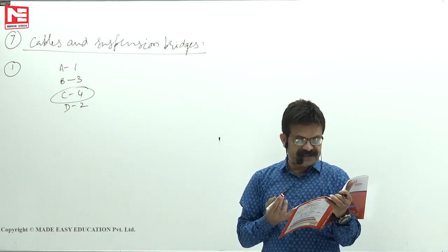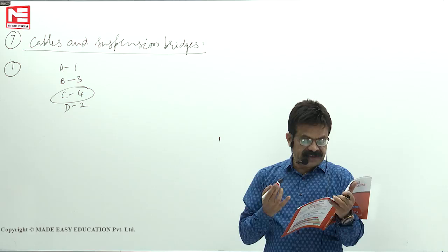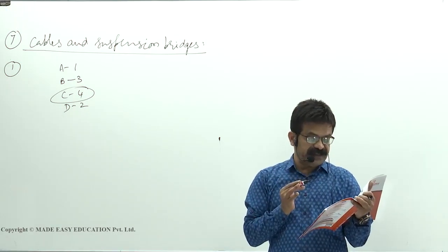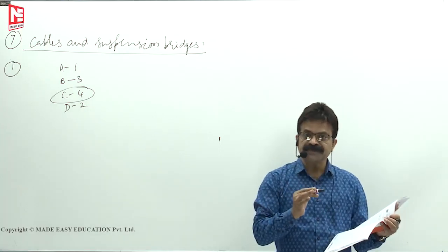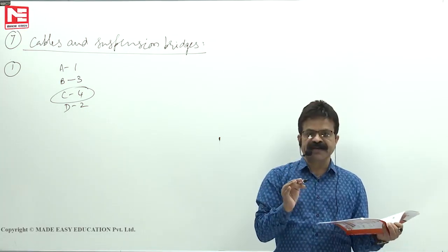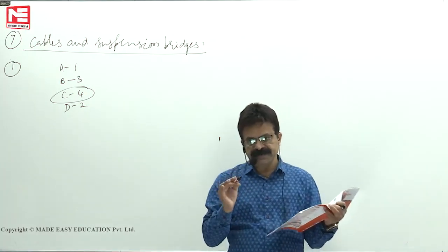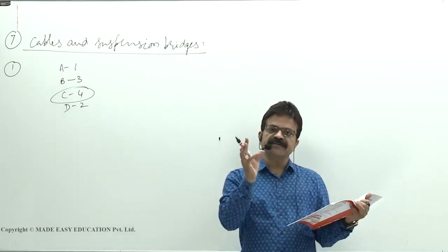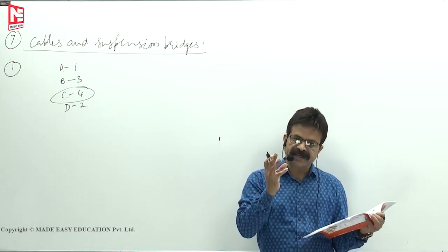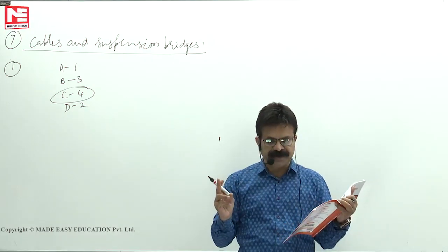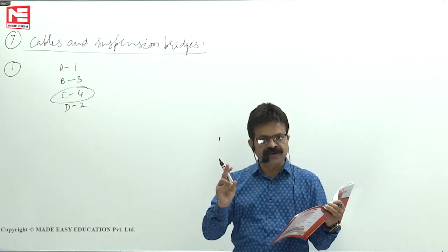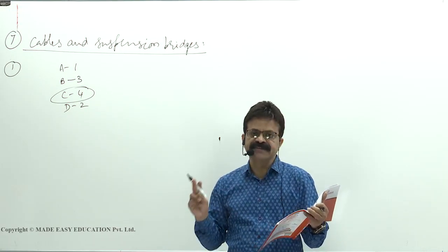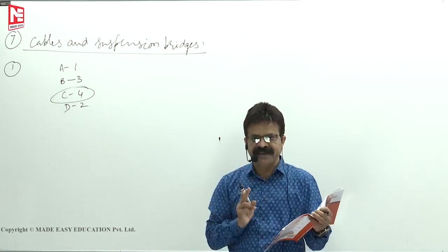Loaded along its length assumes the shape of applied loads. What he actually wanted to tell is that it will take the shape of the bending moment diagram. If you take an imaginary simply supported beam subjected to the same loads, then whatever bending moment diagram it takes, that shape the cable will take.